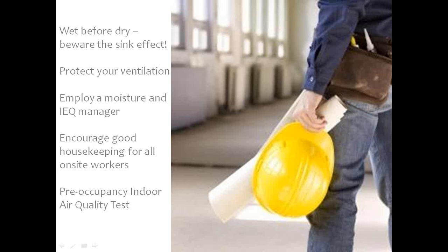Well, we want to protect our ventilation system. You know, it doesn't make any sense to use the permanent ventilation system during construction where the gypsum particles, drywall dust, and other building products can be sucked into the ventilation system to then be blown out onto the occupants once the building is occupied. So using a temporary ventilation system is the best way to take care of that problem.